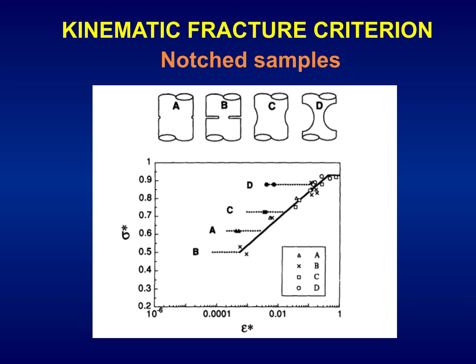Geometry A also has a very high triaxiality level, the sharp notch specimens B and A. Regarding the blunt notch specimens C and D, with the highest radius of the notch, we have a softer, milder effect of hydrogen due to the not so elevated hydrostatic stress gradients.